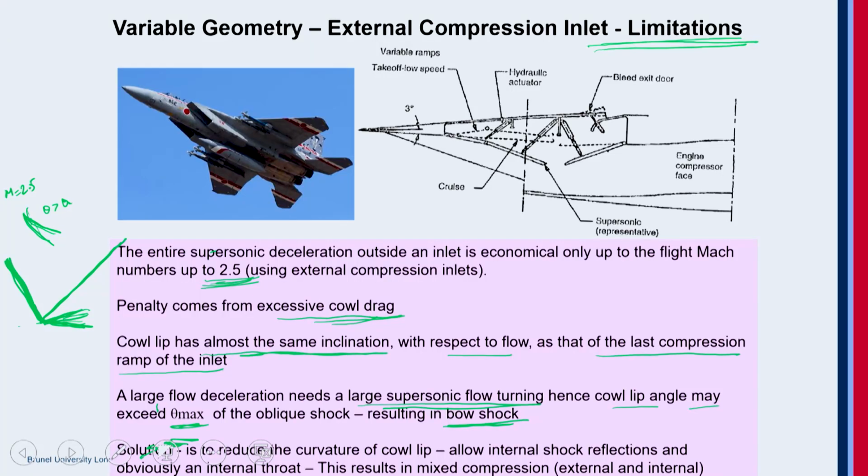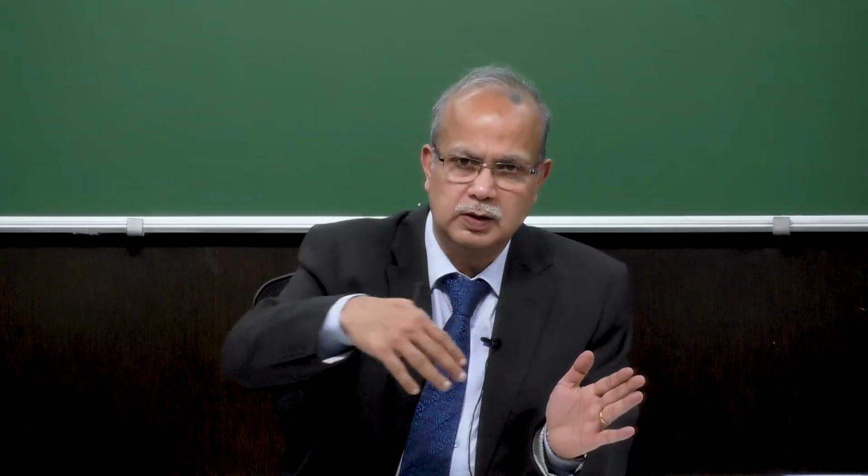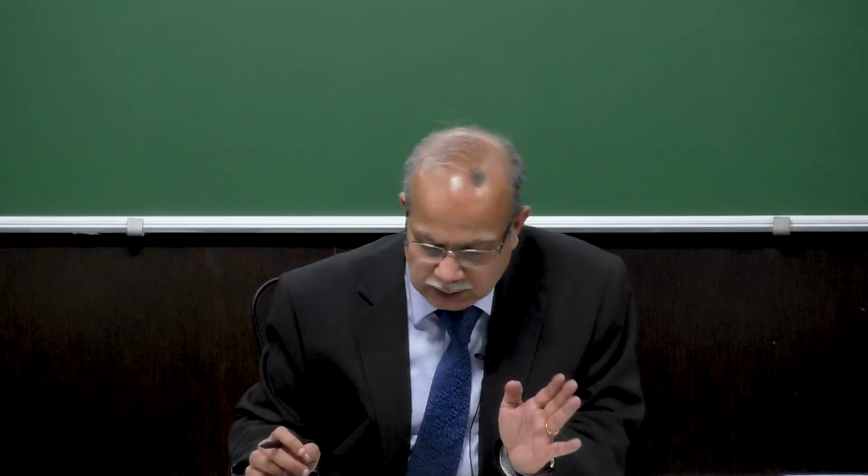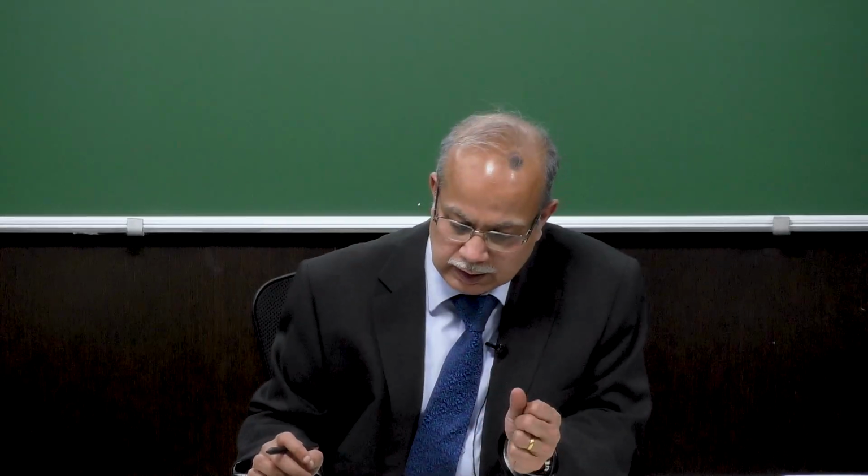inside the inlet. So now you can see that the development is going from the external compression to mixed compression, where you compress not only externally but also internally through the reflected oblique shocks here. So that is what is called the mixed compression inlets.